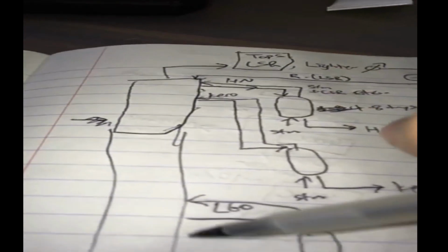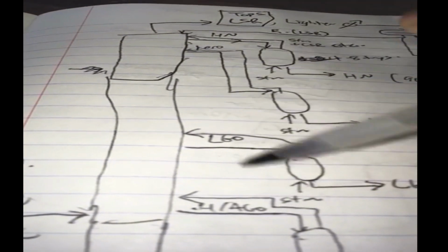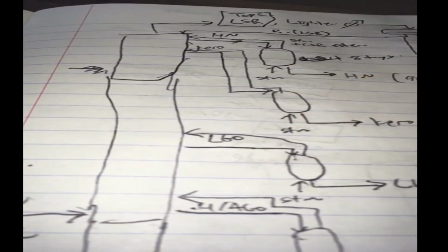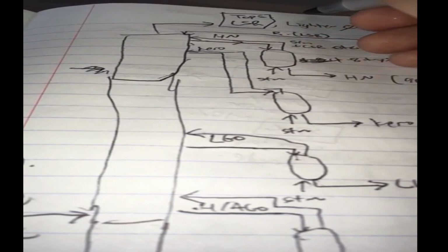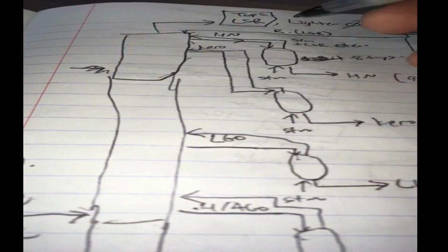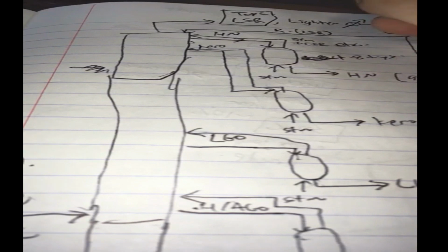Multiple or single? Well, with a single one, we have less control, because we only have one reflux ratio to play with to control the tower. So if I adjust the reflux here, then every stream will be affected. The purity will be affected. So if I want to have fine control over every section of the tower so I can manipulate one at a time, I can have a reflux here.